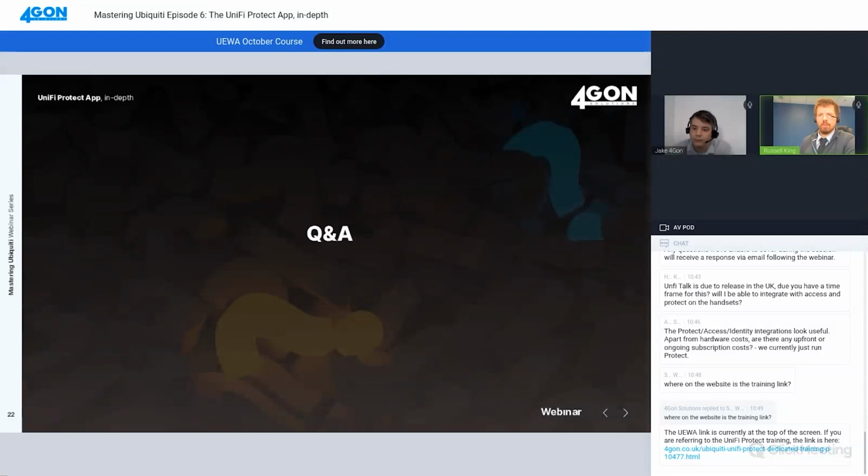You can go into the web user interface of the camera using the recovery code, and then factory reset it from there, or change which direction it's pointing in, but it's probably going to cause more issues than it's worth. To be honest with you, there's no real migrate camera functionality so far as I'm aware. I've never seen it. It's going to be best just to remove it from the original Protect and add it to the new one in its factory default condition.